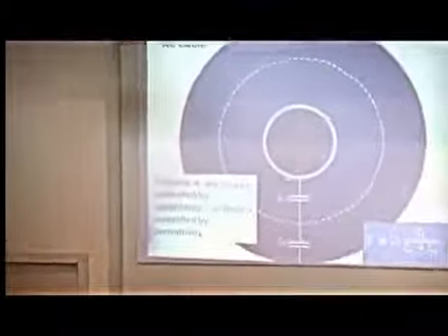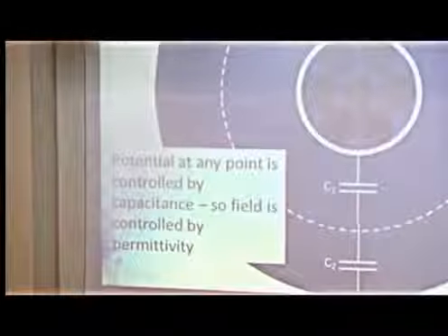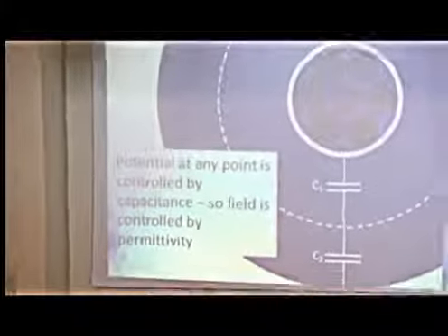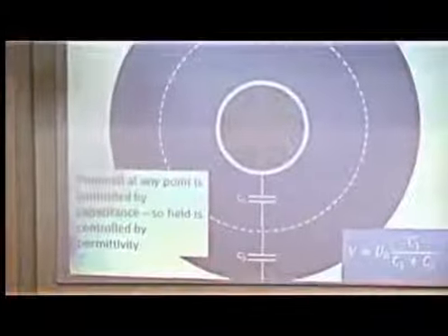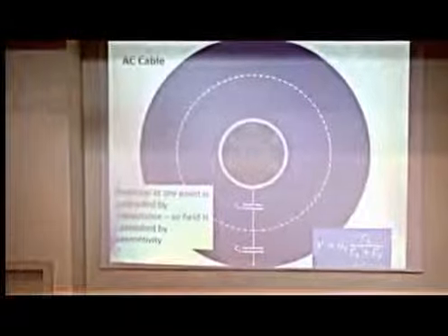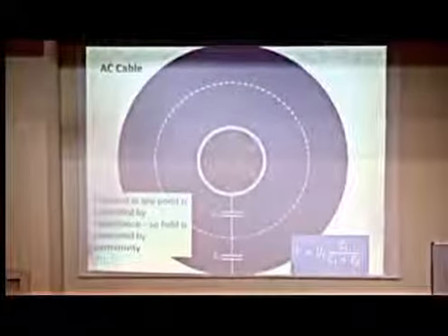But since the permittivity is relatively independent of anything, it's relatively independent of temperature, for example, and it doesn't really change with age, then you can be pretty certain that the potential distribution across your cable is pretty well defined at any time in the future.